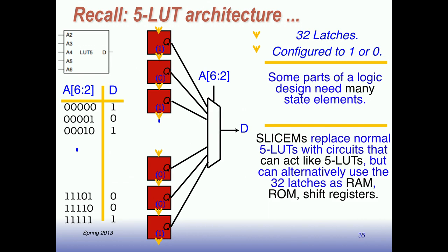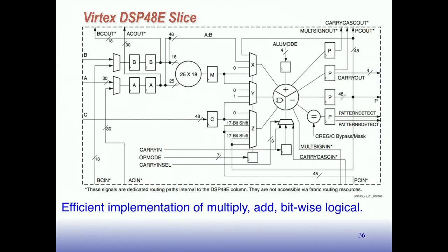there's special blocks inside the FPGA that make multiplication. They're dedicated multiply add blocks. They're called DSP slices. DSP stands for digital signal processing because these were put in initially to make digital signal processing more efficient. If you know about filter design and the kind of stuff you learned in 16B, there's a lot of multiply adds. To make FPGAs efficient for signal processing, they put these DSP blocks in, which are really ALUs. And the ALUs have a multiplier right here. In this version, it's a 25-bit by 18-bit multiply. Right? And also has an adder here and a logic function block here. So it's a general purpose ALU that also has a multiply function in it. So for those applications that have lots of multiplies and adds, they can take advantage of this and save the LUTs for other functions.